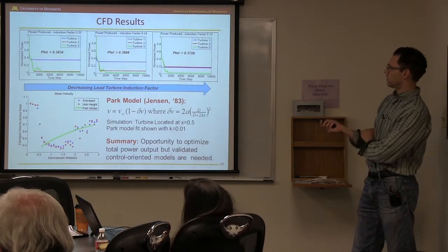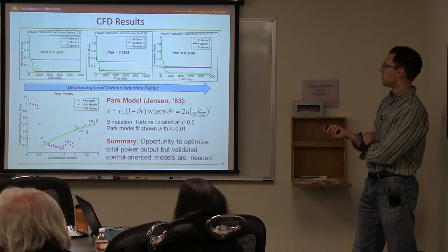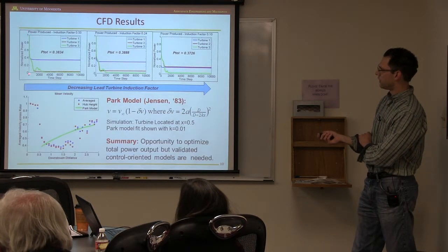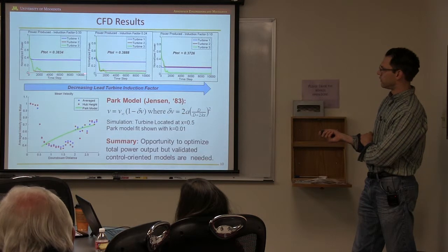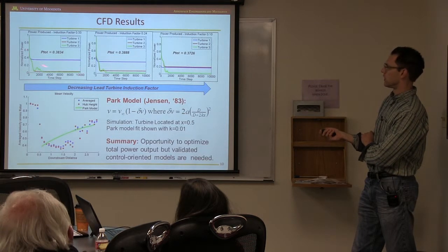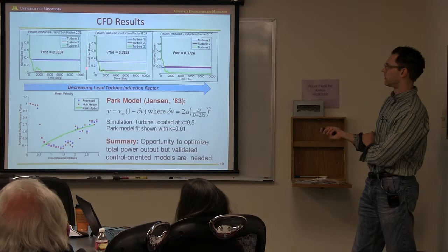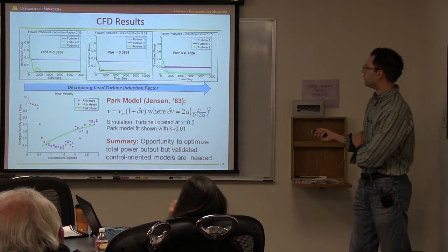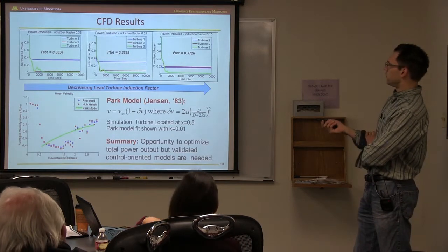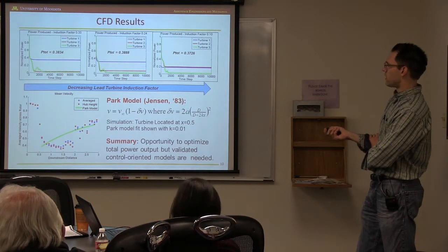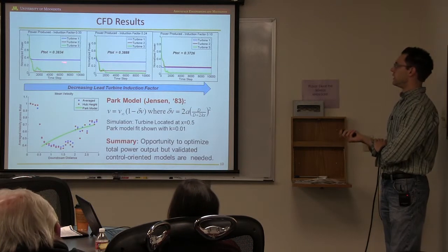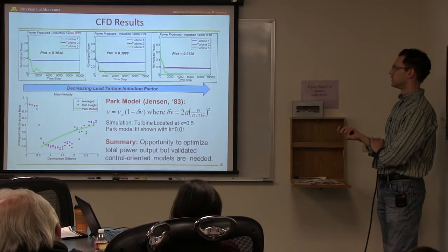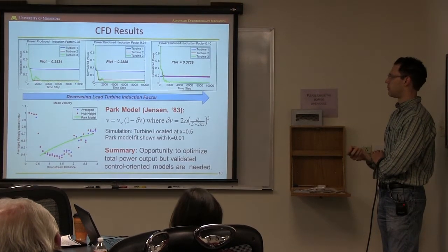The first result is from the CFD code from St. Anthony Falls. It's a 3 turbine result. So this is normalized power for the first turbine versus time. And there's a transient. Okay, we set some boundary conditions. So really we're looking at the steady state, which is out here. And there are 3 turbines. So 3 simulations. Basically, the turbines are separated by 5 rotor diameters. And then in the first case, we operate all 3 turbines at the optimal induction factor, which is 0.33. So you operate them optimally.